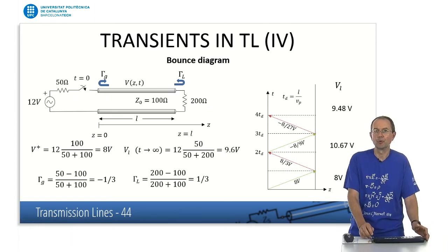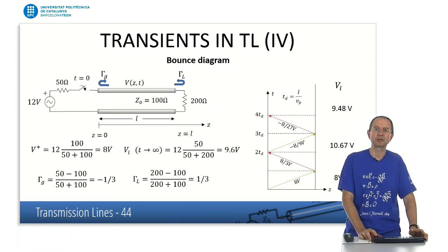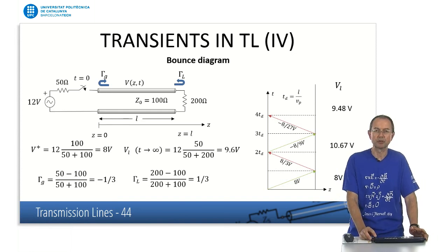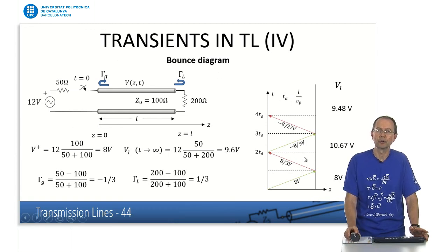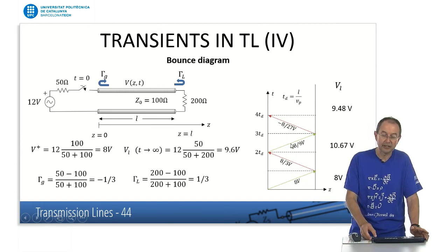So if you work with digital systems and communication between computers or digital devices, you have to be careful. Sometimes you see, for example, connections between these or high-speed devices that are terminated by resistors. The reason for that is to avoid these undesirable situations, transients, which are just going back and forth, and this actually can provide errors, transmission errors between digital systems.